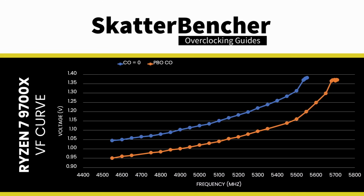Here you can see two VF curves of the Ryzen 7 9700X: the default curve and the one from overclocking strategy number 3 with the minus 35 Curve Optimizer. We can see the law of diminishing marginal returns in action. The higher the frequency, the less additional frequency with every step of additional voltage. For example, on the default curve, increasing the voltage from 1.1 volt to 1.2 volt gives an extra 350 MHz, but increasing from 1.2 volt to 1.3 volt only gives an extra 150 MHz.